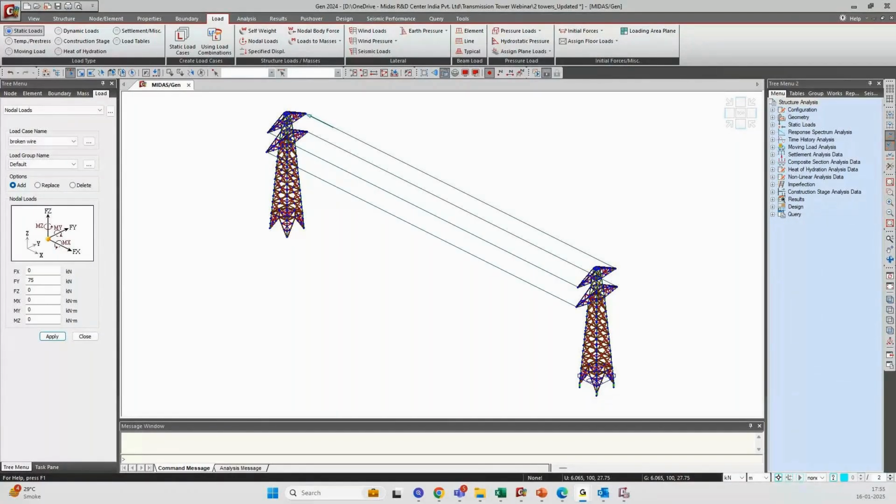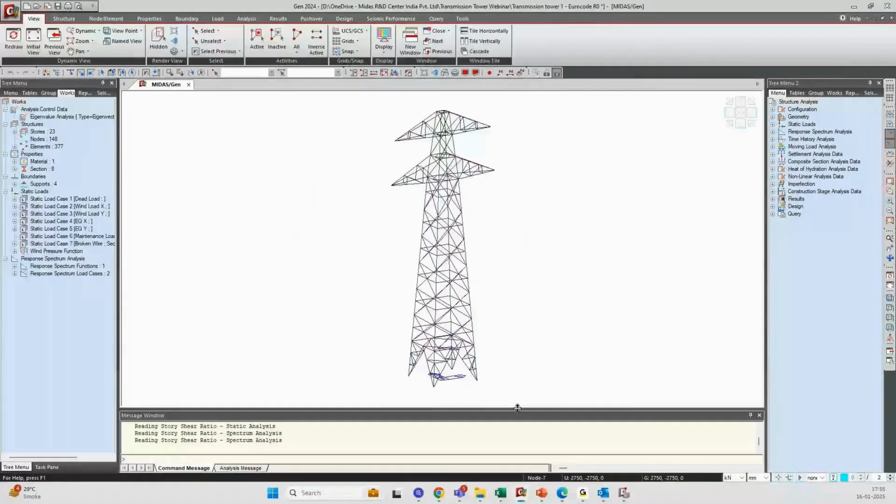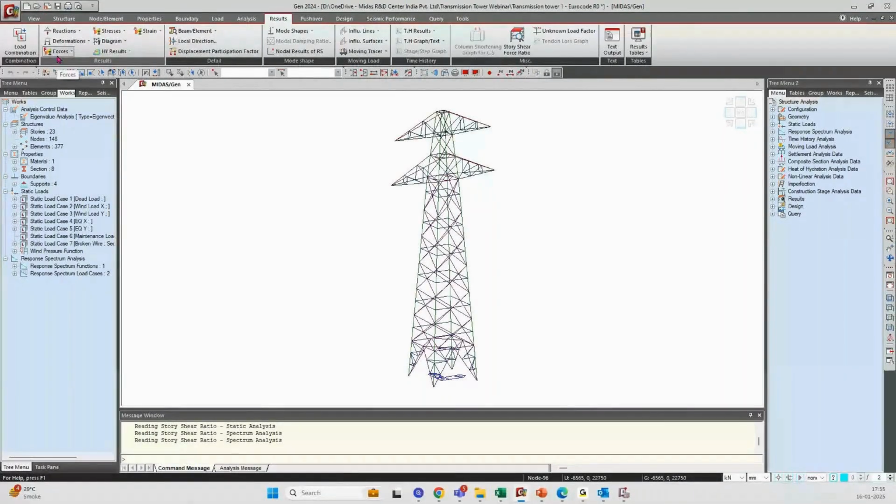We have to perform all of them for the tower design. Okay, actually it depends upon the analysis, what type of analysis you want to do. Like if you want to do the entire thing in a single model, then you can go for the construction stage analysis. So the simplest thing is the linear static analysis. Okay, if you're satisfied with linear static analysis, it is okay. Otherwise we can go for buckling analysis. As the structures are very slender, we can go for the buckling analysis.